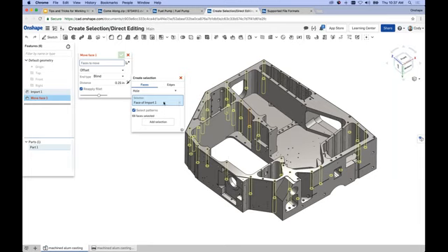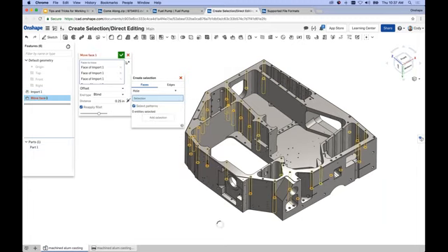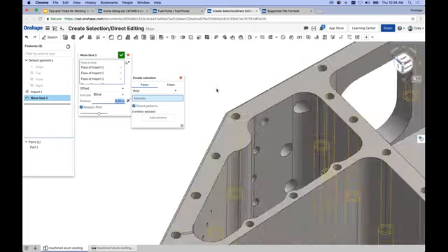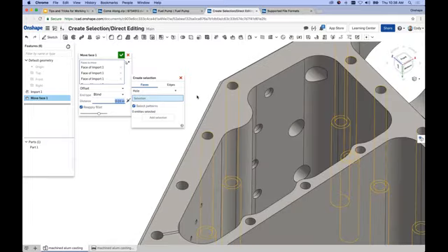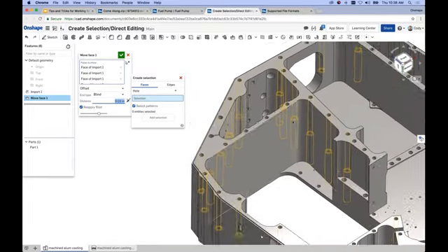Just in this case, with a couple of clicks, it will find all of the patterns, it will select all the faces associated with the hole, and I can hit add selection, right? And now I'm offsetting, it's in essence, probably 20-something holes, with just a couple of clicks. So here's 0.03, and if we zoom in here, now I'm offsetting all of these holes by 0.03 inches, right?